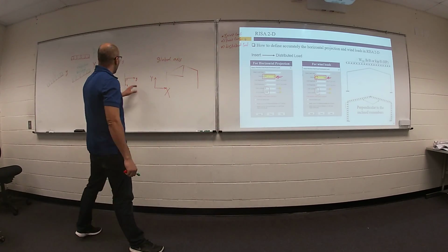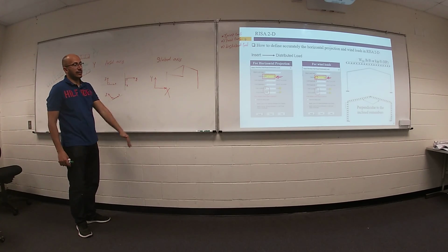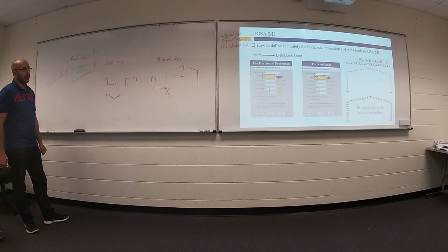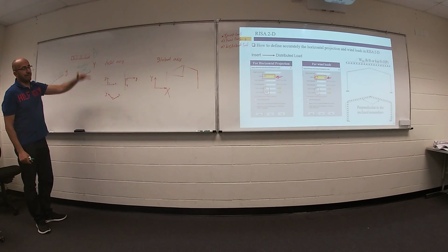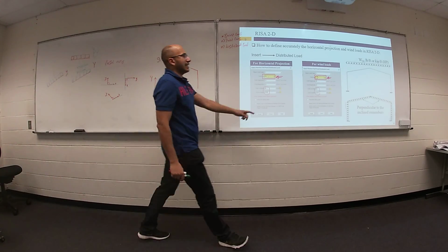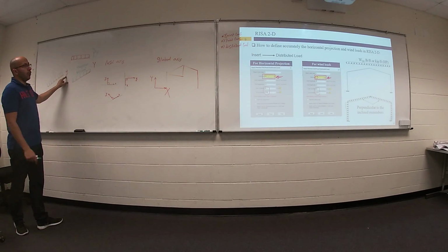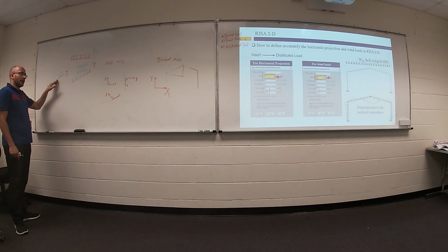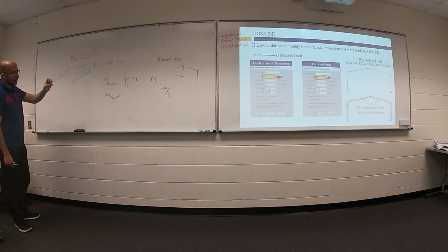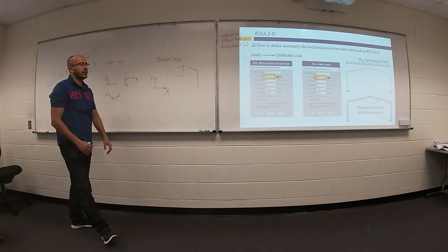One of them, capital Y, is the normal vertical direction, inclined projection. Other one, Py, means horizontal projection vertically, which is this case. Third case, small y, means local direction for this member. If you choose y, the local direction in y is perpendicular to this member.